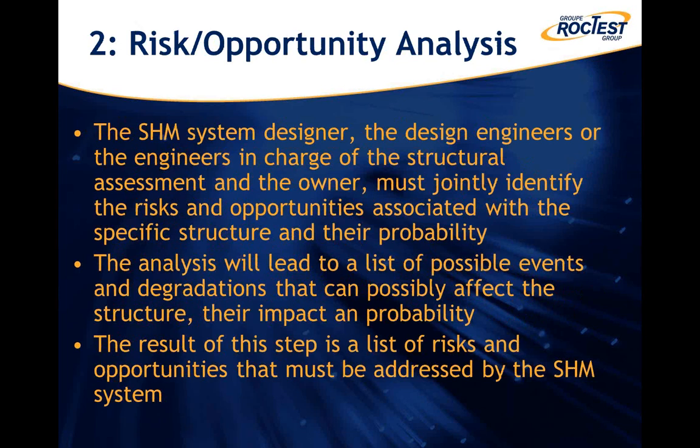Once a specific structure has been identified, then the SHM system designer must work together with the engineer who has designed the structure and the owner to identify what risks and what opportunities are associated with a specific structure. An example of risk would be corrosion, settlements, damage from earthquake. An example of opportunity would be residual or additional load carrying capacity, or better condition than expected, or stiffer structure than calculated from finite element analysis.